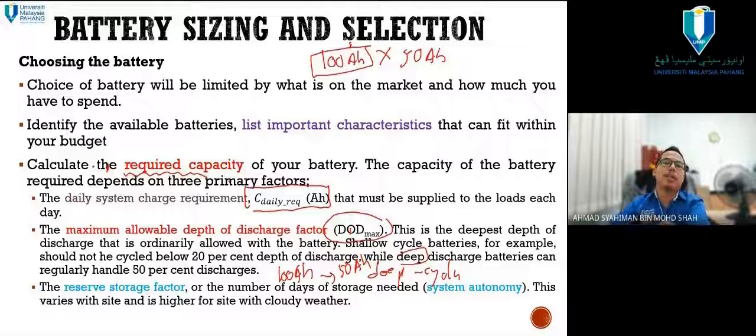Like that. Okay. This one is for the case of VRLA, valve regulated lead acid, or the deep cycle lead acid battery, or for AGM, I think AGM slightly higher than that, maybe 60. Depends on the data sheet. But by default it's like that, the way of thinking. Don't use the car battery or the motorcycle battery, that is the worst.